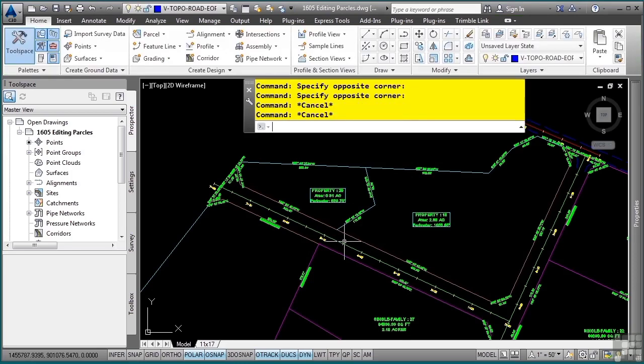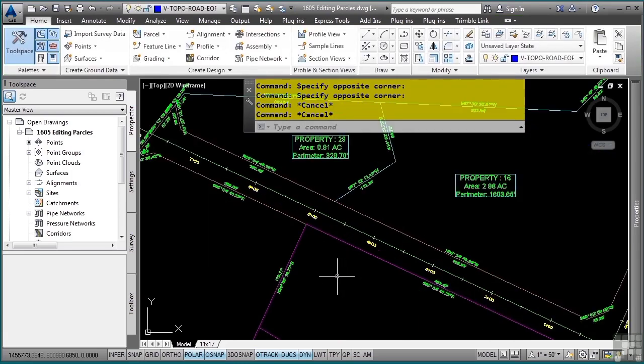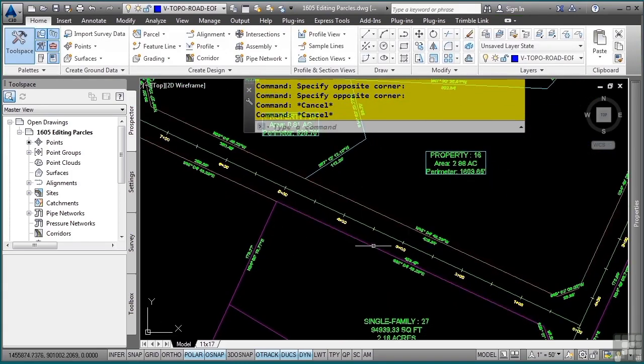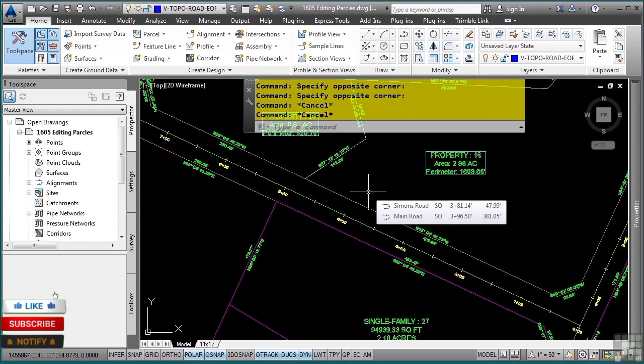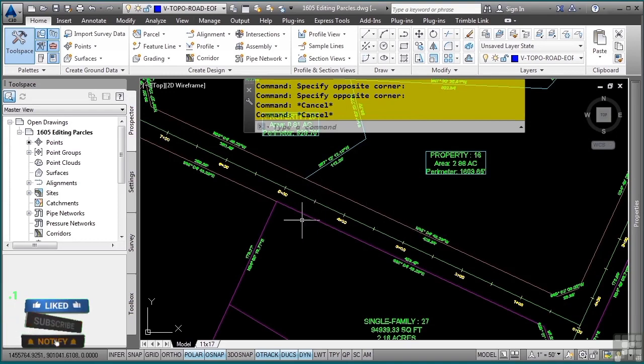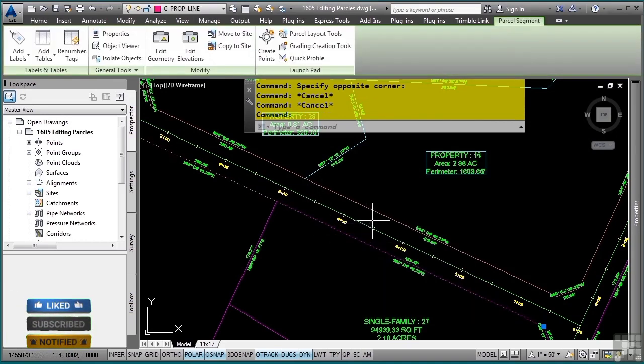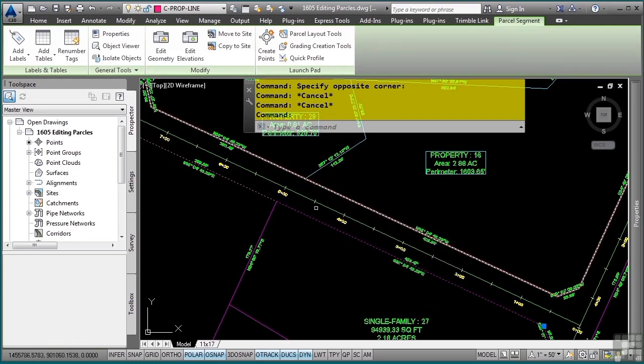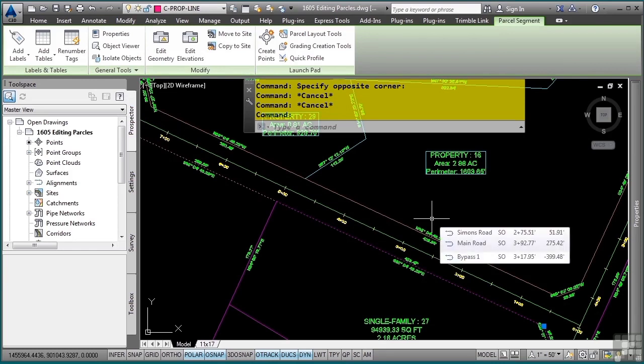Pretty simple stuff. Now, as we look at our drawing, we notice that some of the properties are different regarding the abutment of the road and the property parcels. Parcels have the ability to have a priority. Because this parcel segment here and this parcel segment here, as well as all the additional ones, share a line between two parcels, you need to define the priorities to tell Civil 3D which parcels should govern for plotting.